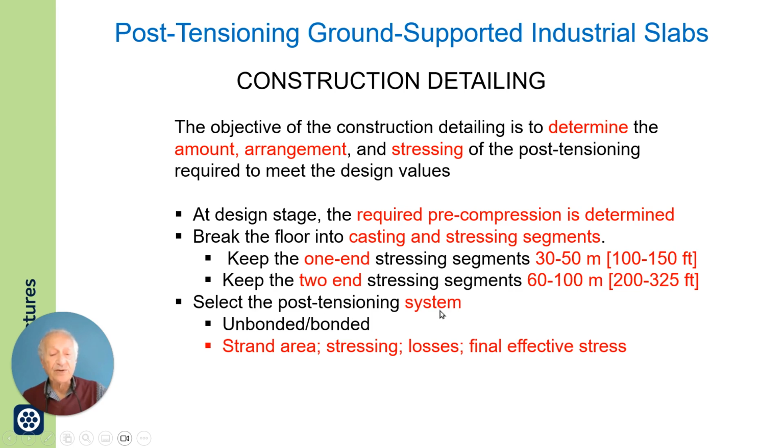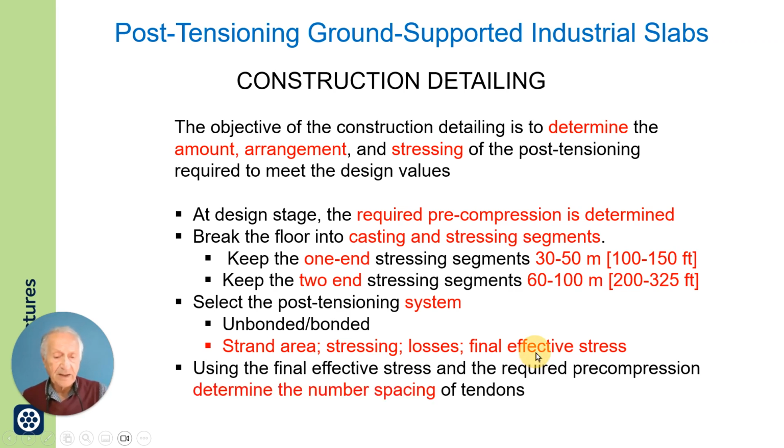Select the post-tensioning system, unbonded or bonded, and then you know the strand area, you know the stressing, you can calculate the losses and find the final effective stress that you use for design.